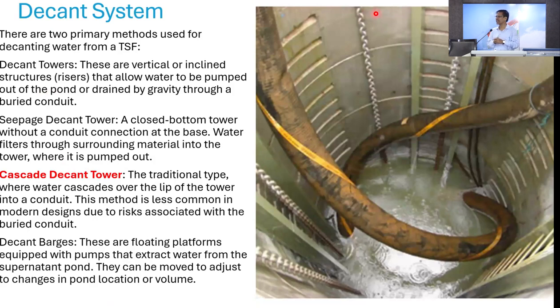This is not a new thing. This also we do in hydropower when you have got a tunnel. Suppose in a tunnel I am putting the water, and suddenly that is called a surge shaft. Suppose I stop the tunnel for some requirement, where will the water go? It will push back into the tunnel and crack it, burst it. So there we do the opposite way. Here I am taking the water vertically downward, but there I take the water upward.